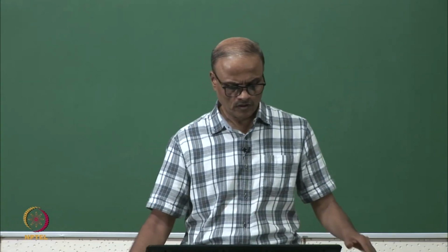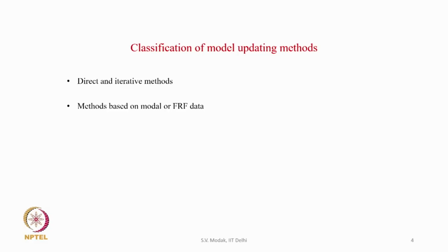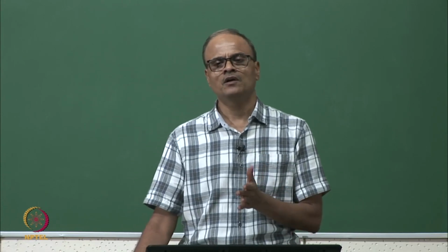The other classification can be based on whether the model updating method utilizes the modal data obtained from the model test, or whether it utilizes the FRFs measured in the model test. So some methods are based on measured modal data, while some methods are based on measured FRF data.